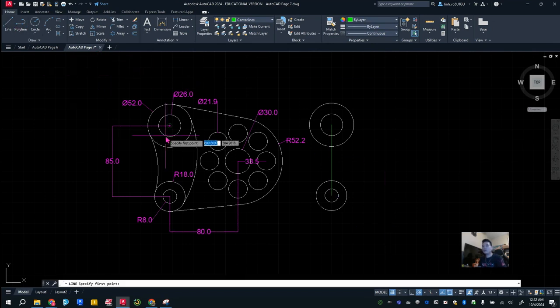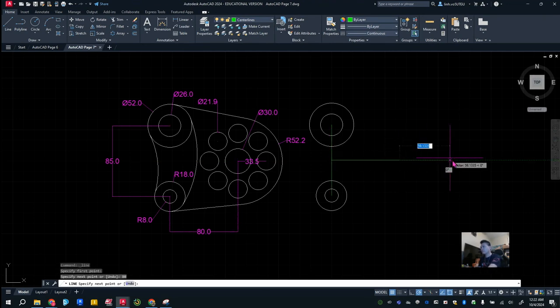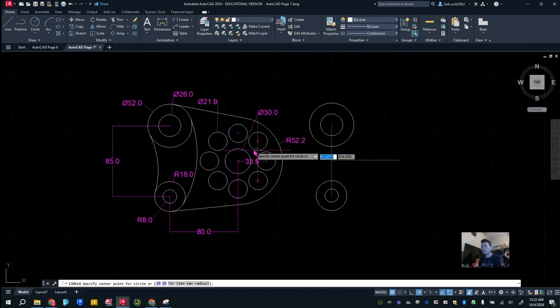I'm just going to click on it, and here's where I'm going to assume that this right here is in the center of the distance from here to here. It's halfway, so I'm going to go to the midpoint and then to the right 80. I'm assuming that center. So now that will give me the location where I can draw this circle of diameter 30.